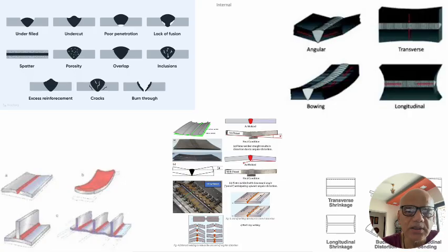Indirectly we can see it based on the depth of the welding and the amount of filler wire he has consumed, and that could be another good indicator whether we have achieved full penetration. Or else for these inaccessible things you may have to use a borescope or some mirrors, or you may have to take an x-ray or ultrasound, and only then will you be able to see this poor penetration.